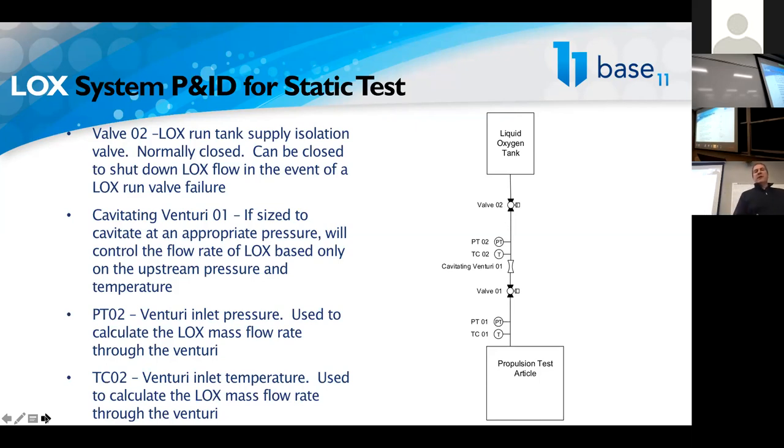I didn't know anything about cavitating venturis when I was a student, so I don't know where you guys fall in that. Depending on where you are, from freshman to senior, you won't know about a sonic venturi until you take compressible fluids. It's called a sonic venturi because the gas going through it will accelerate when the flow contracts going to the throat. It's going to accelerate until it gets to a critical pressure ratio where it's choked.